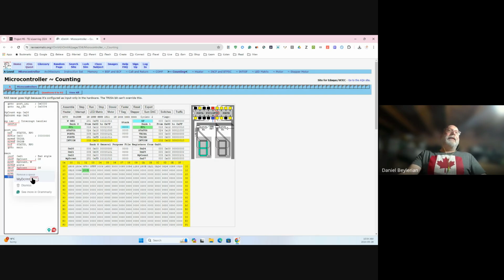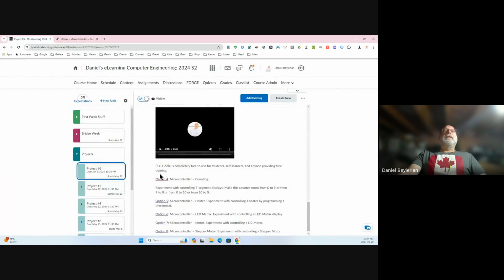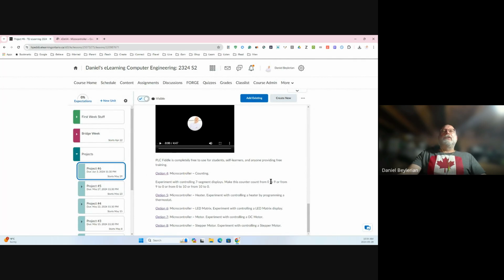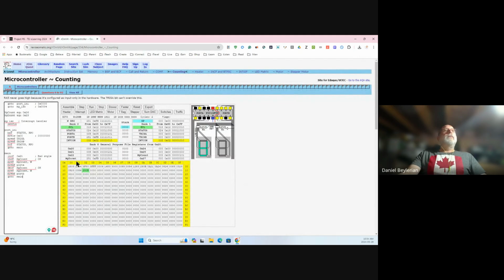So your job, like I said before, is to make this count from 0 to 9, or from 9 to 0, or from 0 to 10, or from 10 to 0. Rehearse it, make the video, demonstrate what's happening, explain what you're doing here in the code. You can copy and paste and add more code here. How do you make it show a 10? Well, you'd have to turn on these segments right over here, these two that I'm pointing to, and of course, these 6 segments to create the 0. The 7th segment in the center, you're not going to turn that on.